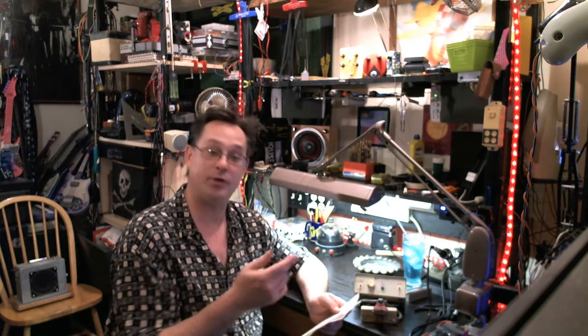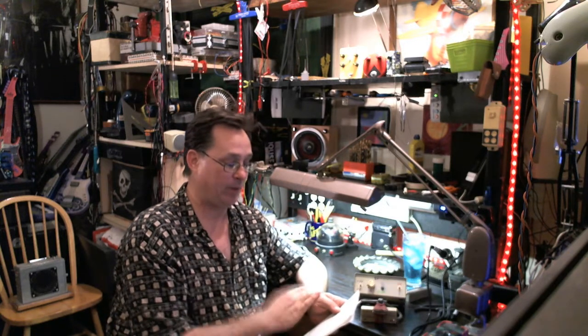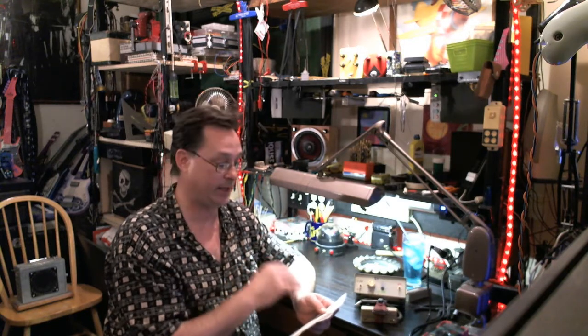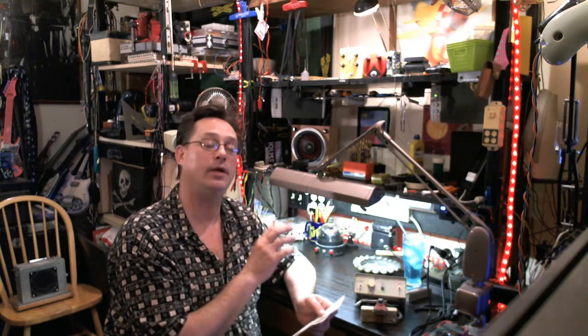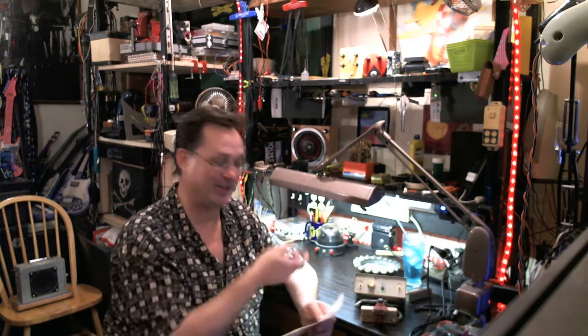Another use for this, it produces a relatively pure sine wave. So in theory, you could hook this up through your pedal to an oscilloscope, or download a program if you don't have an oscilloscope. What that would enable you to do is see the waveform. You can actually see the audio wave, and because this is a sine wave, which is a nice looking wave, it's similar to what the guitar wave naturally looks like. With a fuzz pedal or distortion, you could see exactly how the waveform is clipping or distorting. So you'd also have a visual reference point to work from. And if you put a chorus pedal on it, it looks really neat. You can see the voicing moving around in there as you turn the rate up and down.